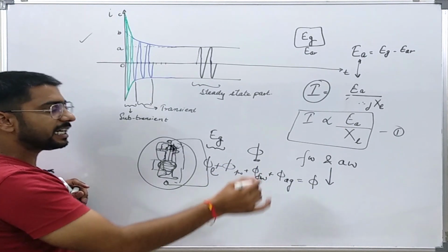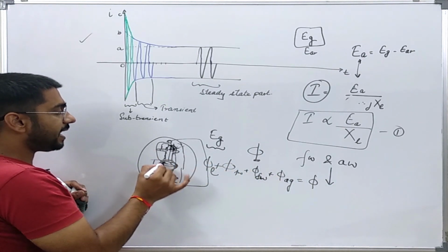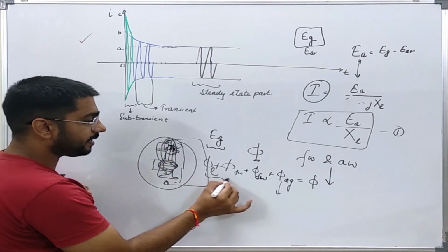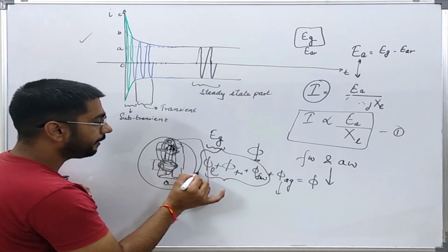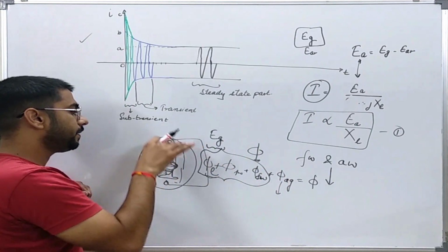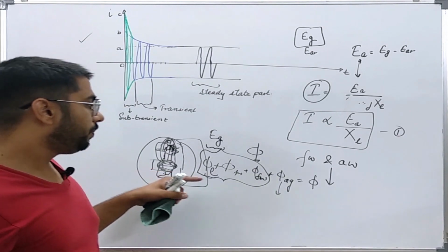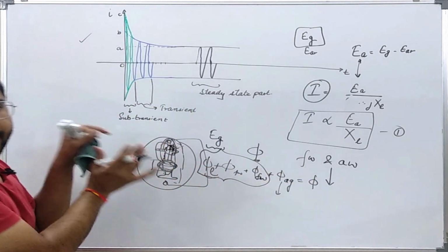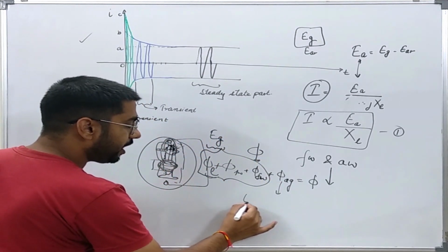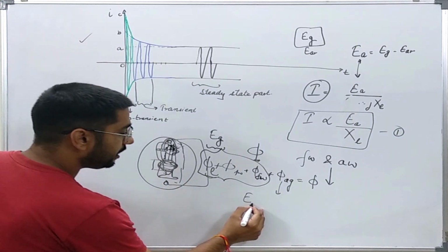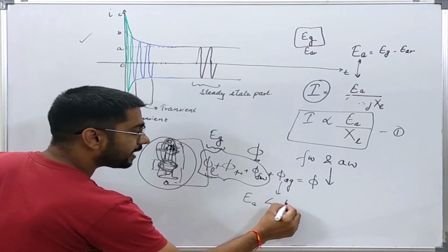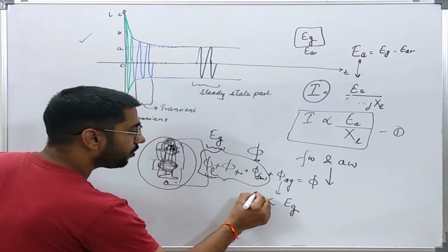However, the flux linking between the field winding and the armature winding will reduce, since these three are not going to participate in the induction of the voltage in the armature. So because of that, what will happen? The final air gap induced voltage EA during the short circuit will actually be smaller than the no load induced voltage.